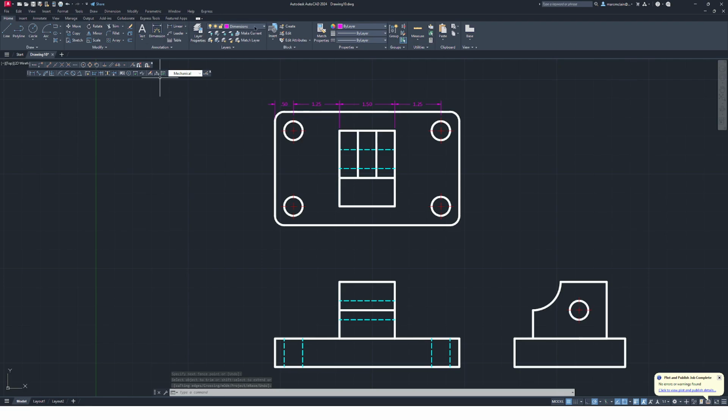Now I can do the same thing here. Go back to my object lines, and I need to come down 0.25, go over 0.5, and go back up. And then trim that off in the center. And that will create a hidden line over here. So back to the hidden lines we go. And we'll go there to there. And then that's got that.